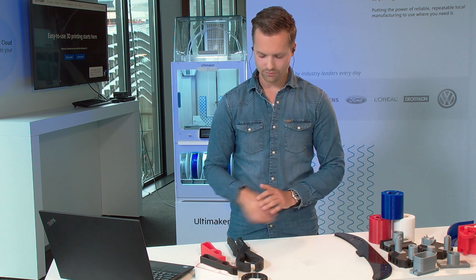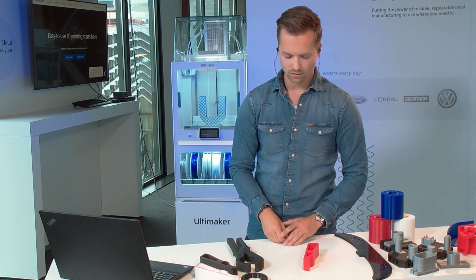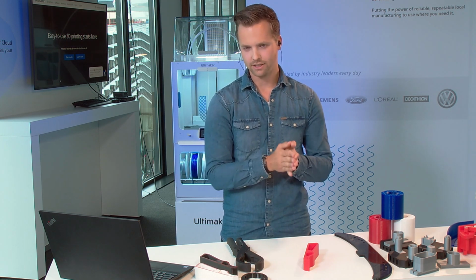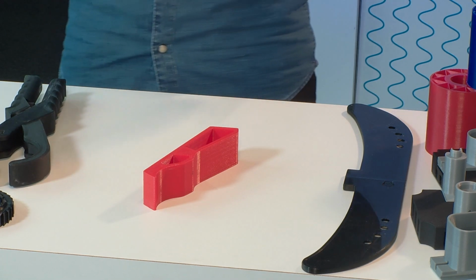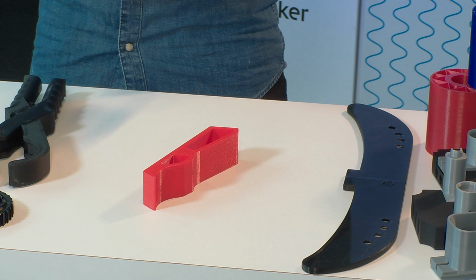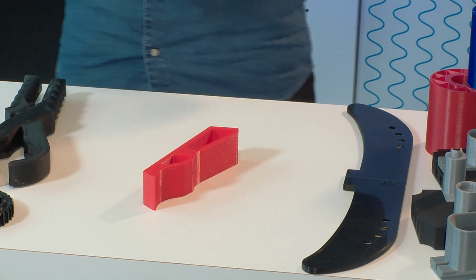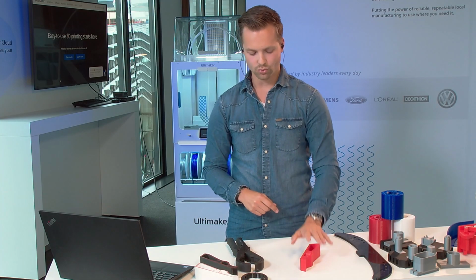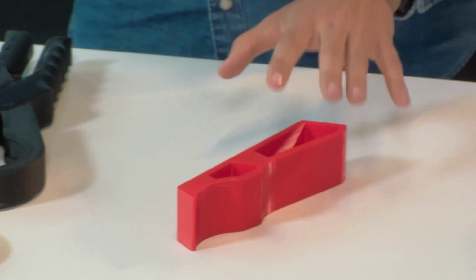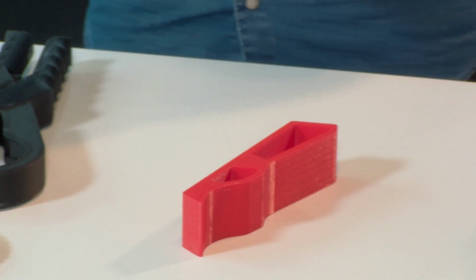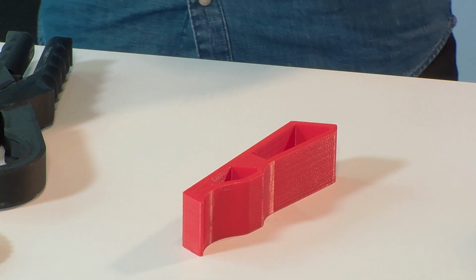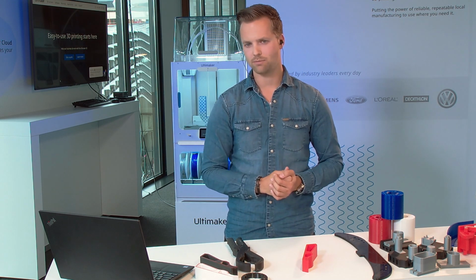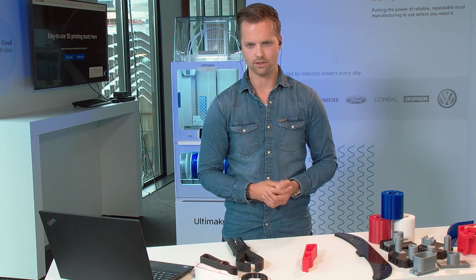This is one of my favorites. It's called the can pusher. Imagine if you have one stream of cans coming in the machine, and it's divided over three conveyor systems. So one is going through, one is put in the second line, and the other one is put in the third line. This basically pushes these cans towards these lines. The original part was about a third of the height of this part, so there was not that much contact area with the can, and it was also on the top. So you can imagine that these cans might tip over and lead to jammings in the machine.